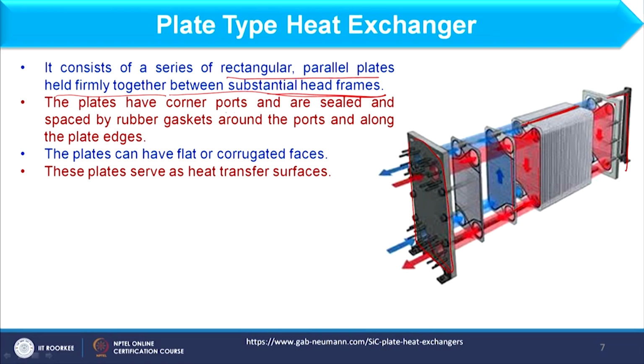And plates have corner ports and are sealed and spaced by rubber gaskets around the ports and along the plate edges. Okay. Now, what is this? If you consider each plate, either this plate or this plate, each plate will have 4 corners. Fine. Now, what is the purpose of these corners? The purpose of these corners is that they let the fluid enter or pass through.